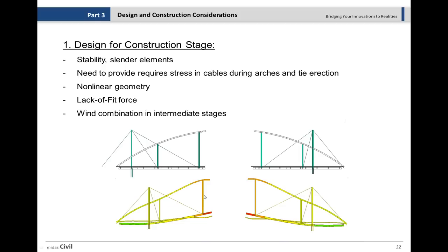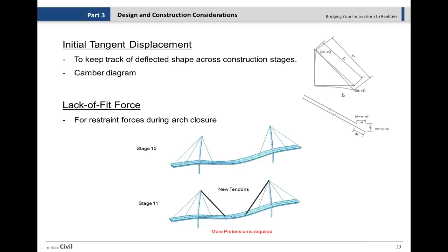Then you see nonlinear behavior of the structure and also the cables, which you can see here. When we have that additional displacement, with large displacement, we cannot assume that they are linear. It becomes geometrically nonlinear, and if you're doing the analysis with any software, you definitely have to run a geometric nonlinearity analysis.